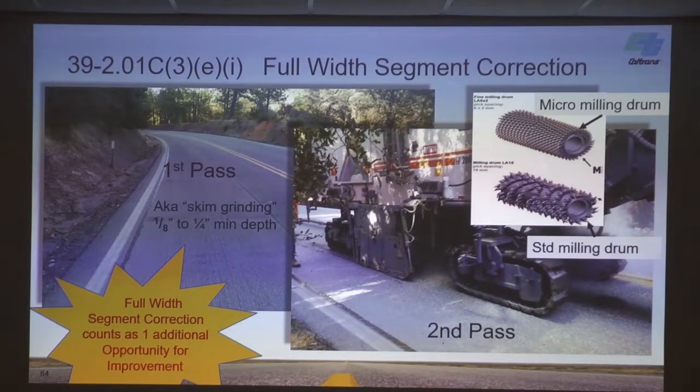On jobs where I had to get down below 50, we used mills and we set the automatics. And this spec would defeat that because it might be a quarter inch at the center. But we used automatics because they can go 2%. When we got to the outside, because of overlays, it builds up on the outside of roadways more often than not. We would be 3/4 of an inch deep on the outside, and we would be paid to that. Using the automatics in the machines helps extremely, because we took roadways from 180 to down below 60 because we used the automatics. It wasn't because we were just profiling.